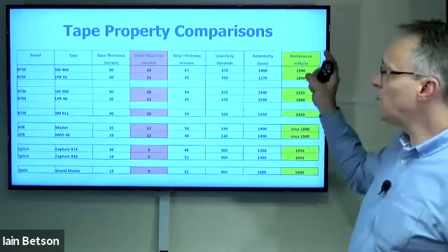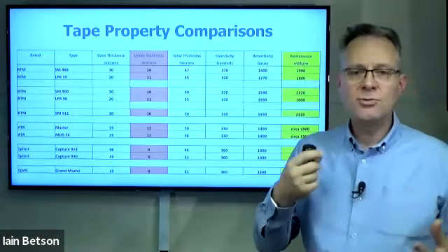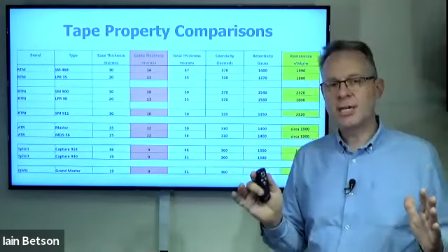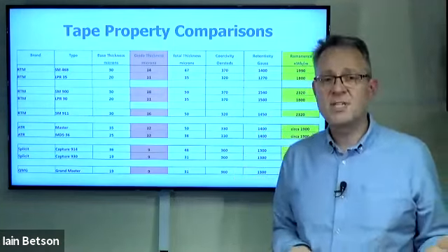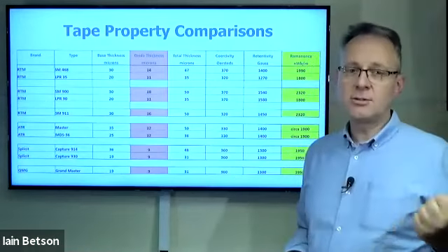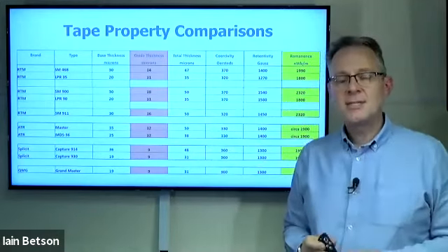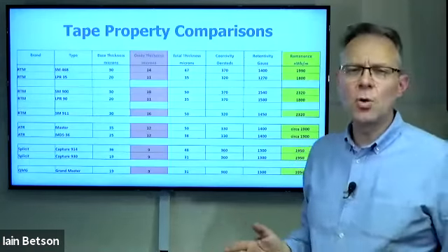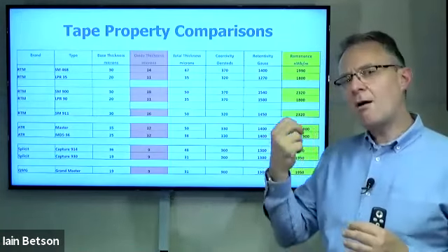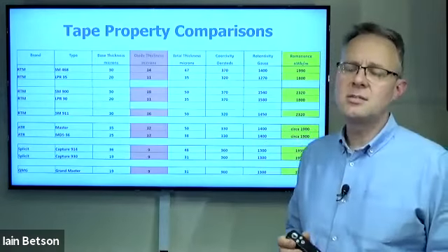Well, as I said, if you've got a very thick oxide thickness, you're going to need quite a machine to drive it. And quite honestly, no disrespect, I've got an Akai GX4000. I'm using that as an example of a nice little domestic machine. But even if you could step up to something like a Revox A77, or even the B77, those machines, quite honestly, are not going to create the grunt to drive the tape level on SM900 tape to get the benefit of it. Yes, they'll record on it perfectly, but if you're trying to push all that level onto the tape to get a high signal to noise ratio, to get high peaks, to get good remnants coming off the tape, the poor little machine's not going to do it. It just wasn't designed to run on that tape.